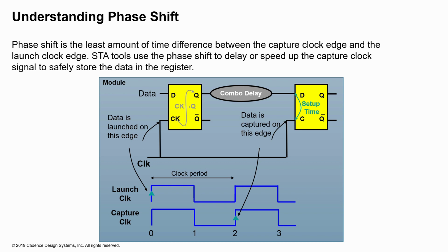All of those scenarios can cause different clocks for launch and different clocks for capture. In either case, in order to accurately depict what is happening in the tool, we can use a value of phase shift to transfer the data between launch clock and capture clock.